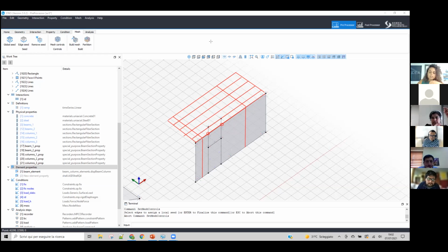Yeah, I don't know. These are different options. Actually, we have some models made like this, but they're simplified. So the rigid joints are collapsed in the point. The section of your pier just goes up and the mass of the pier is proportional to the real mass, but the section you visualize in STKO is as high as this beam. So it does not really account for the part that is a joint. The joint is just infinitely rigid and that's it.